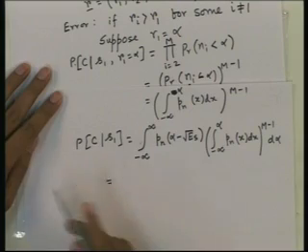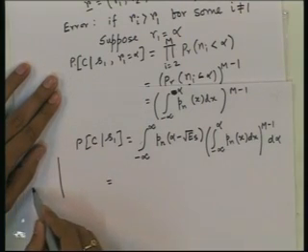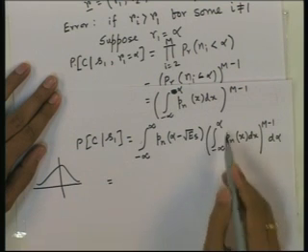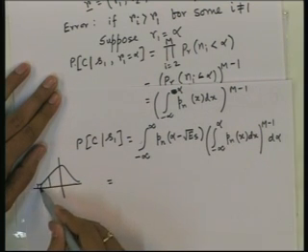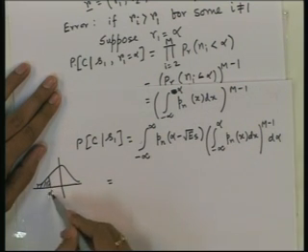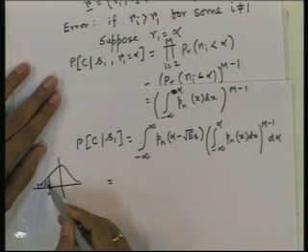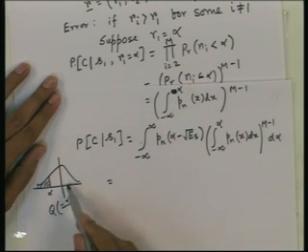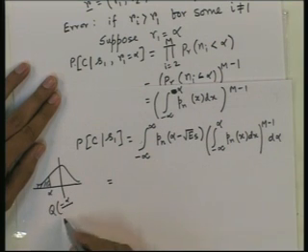So, let us just see, if alpha is negative, what is this integral? If alpha is negative, then this integral is nothing but taking this density function from minus infinity to alpha. So, this is nothing but Q of minus alpha, which is positive, Q of minus alpha divided by the standard deviation of the noise, that is root over N0 by 2.